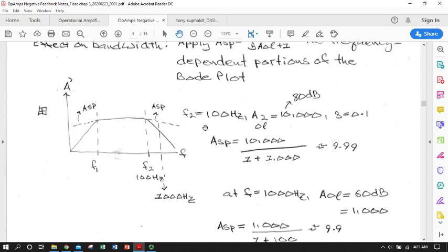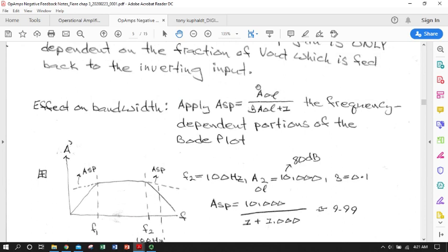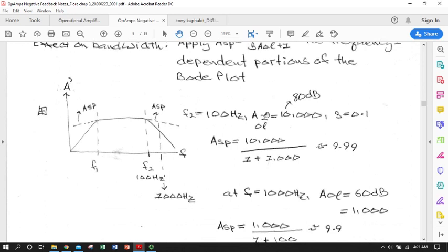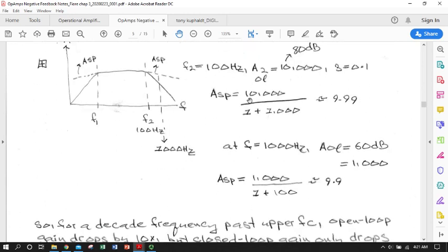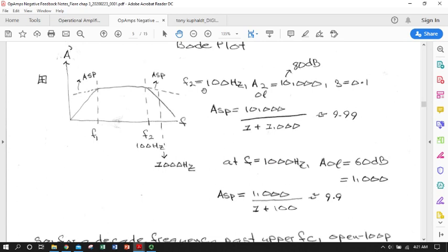And we will go back and forth between decibel and gain ratio as needed. Just a word on that: if you are using this equation that we derived last time for closed loop gain, be warned that these should be voltage ratios, not the log of voltage ratios. As we derived it in terms of a V in and V out ratio, very specifically. Okay, so back to our frequency plot, where we will, unless otherwise specified, be using voltage ratios again.